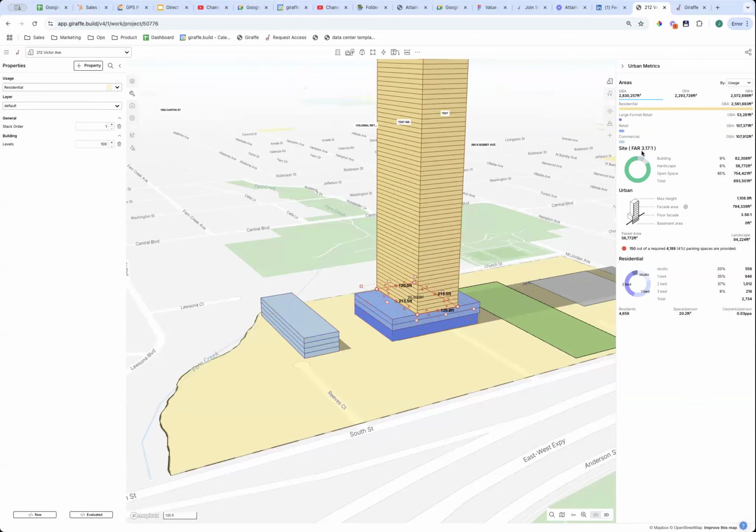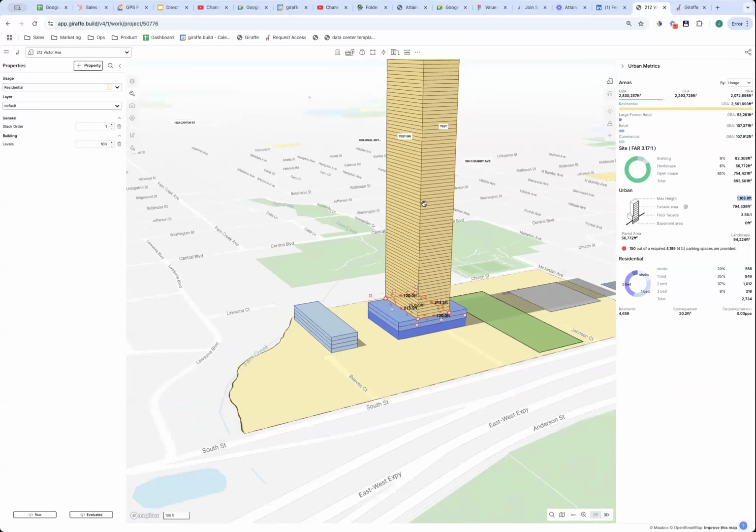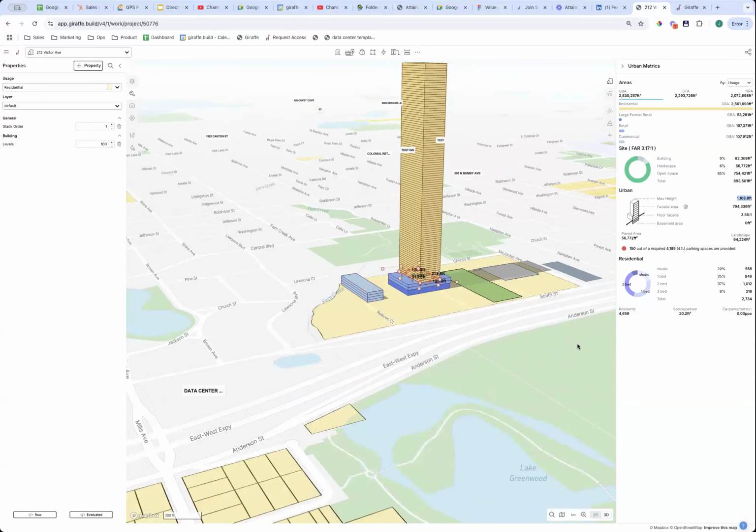So that gross build area is the simplest, and it's basically just reporting back what we've designed. As that then filters down through the urban tab, the FAR is taking the gross area and applying it over the site area. If I then change tab to the net rentable, the FAR changes to be the net rentable over the site area, or the same with the gross floor area. So you can keep quite a lot of control over what the definition of FAR is here, whether using the gross or the net. Max height is taking the combined floor to floors and adding them all together and giving us a maximum project height. Come back to that in a minute.